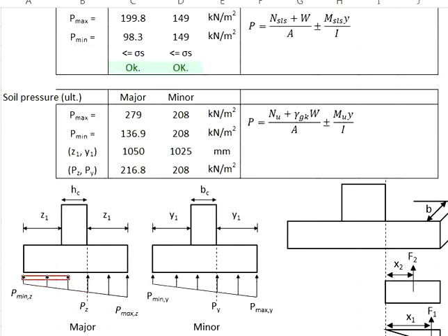Initially, the stress is equal throughout the section. Due to the moment rotation, let's say in this case in the major axis, the stress is redistributed. Some of the stress here will go to the other side, resulting in higher stress in the area against the moment.